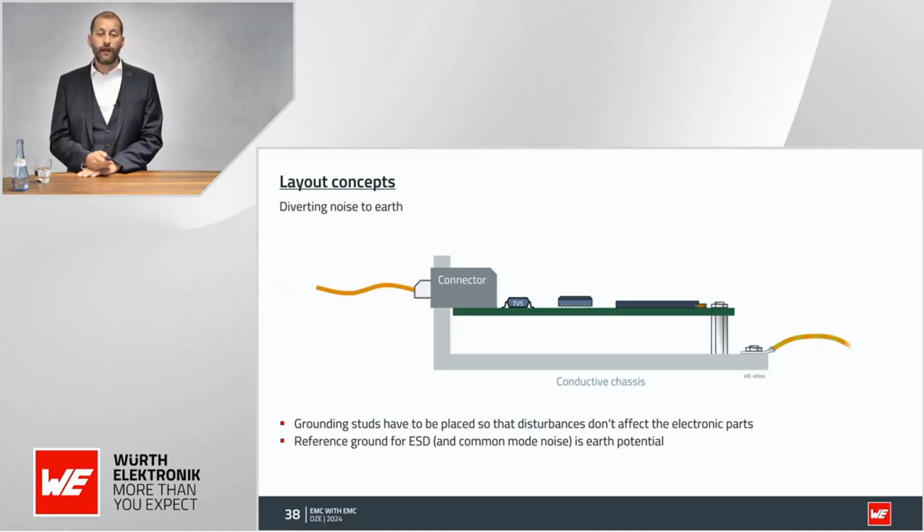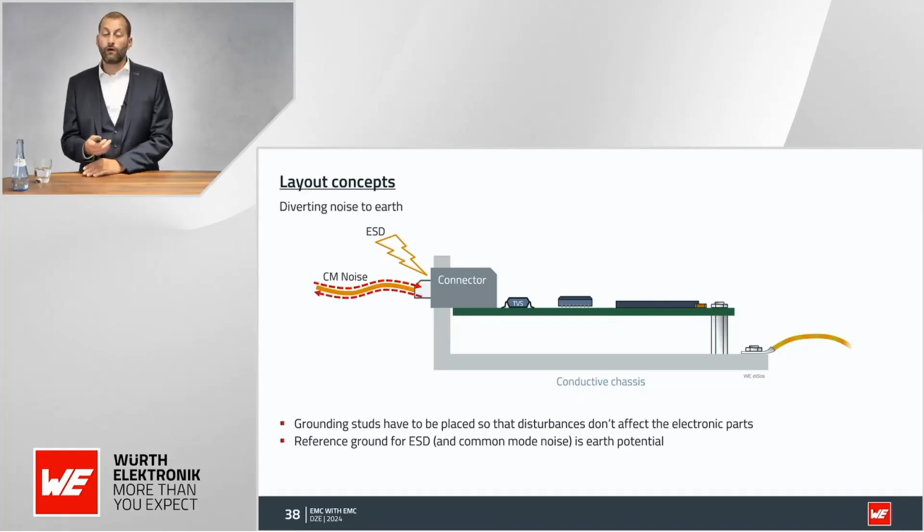If you put a connector into the socket of your connector, you will create an ESD impulse. You also have common mode noise due to maybe radiated emission, or sorry, not emission, immunity. So all of those things cannot be avoided. You will always need filtering, you will always need shielding.